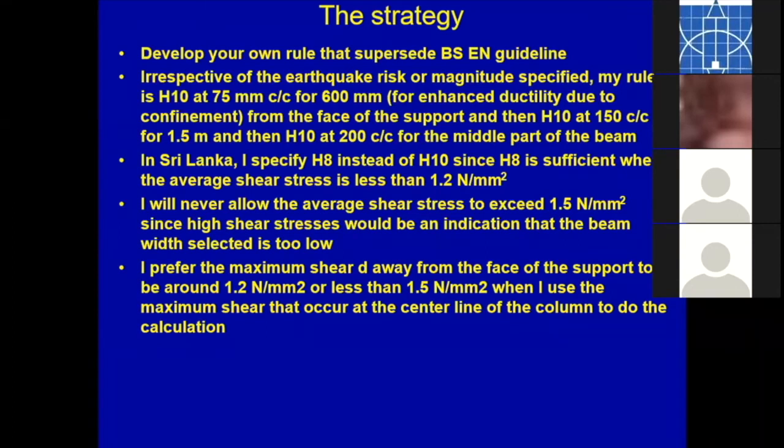So if the beam forms a plastic hinge, there will be plenty of steel reinforcement in the form of shear links to distribute the cracks, and also when stressed, there will be sufficient confinement to the concrete so that the concrete will not crush. So there are so many benefits you can gain by going for earthquake based designs.